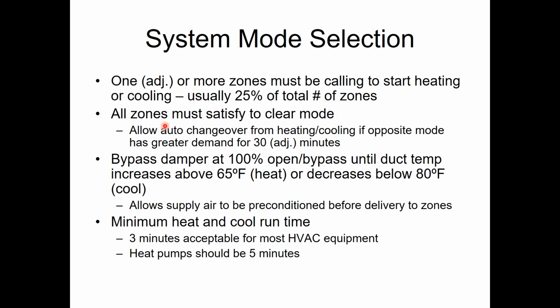If you say, oh, it's not going to work for me, Ryan, because I have this one zone that just needs so much more cooling than the others. It's like a server room or it's a copy room. Guess what? That zone shouldn't be on the VVT system. That's going to be a red flag when you tell me that. Don't put a server room on a VVT system. It's always going to want cooling. It's always going to be a caller, and you can't give it cooling all the time.